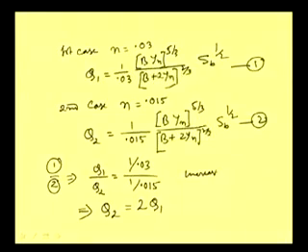Earlier it was Q, now it is twice Q. Earlier it is Q1, that means now it is twice Q1, that means it has increased by 100%. So, increase in discharge is equal to 100%. Well, so that just shows us directly how by improving the channel characteristic, by providing lining, we can increase the discharge capacity or the carrying capacity of a channel, and we can have a better water management wherever is required.